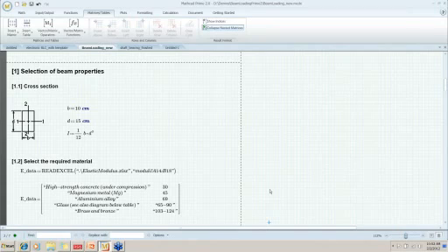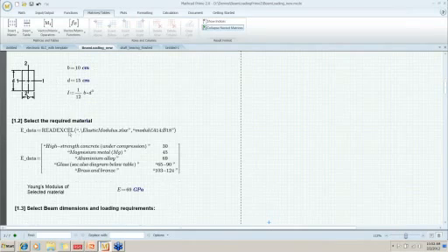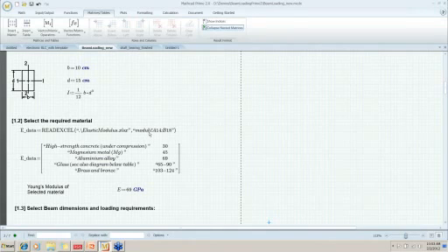And the first thing we're doing here is reading data in from Excel. Mathcad Prime has some new functions called Read Excel and Read CSV. So you can read data in from Excel. You just give it the path to the Excel file, and you could even give it the specific range of data to read in, and the worksheet. There's a worksheet tab called Moduli. So we use the standard Excel notation, the sheet name followed by the exclamation point, and then the starting and the ending data cells.